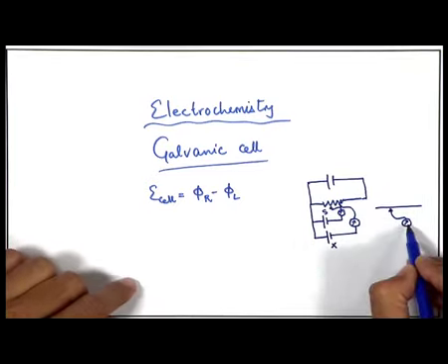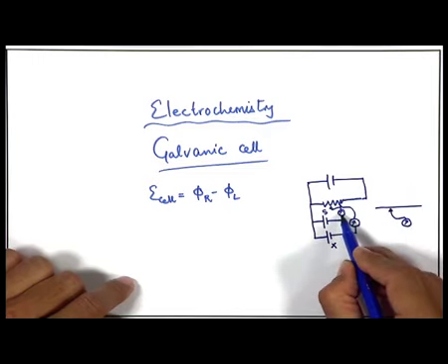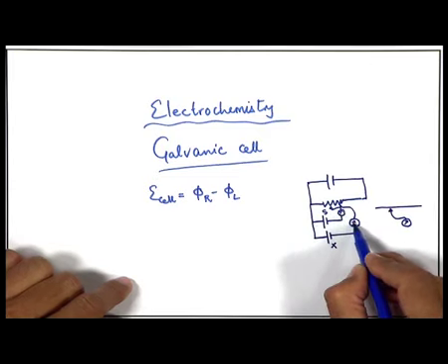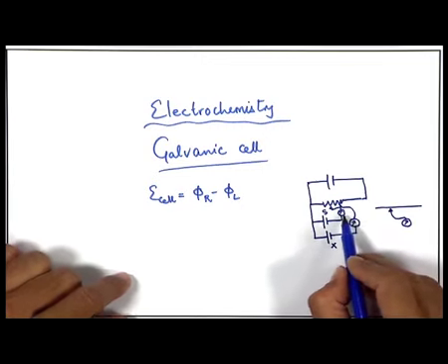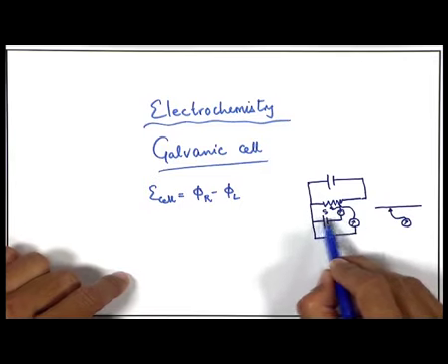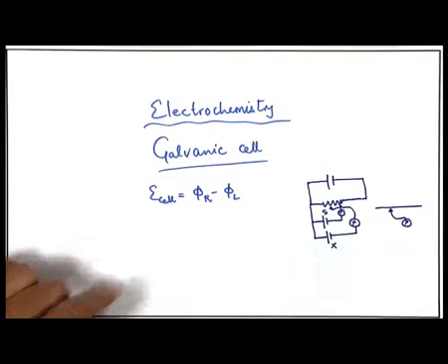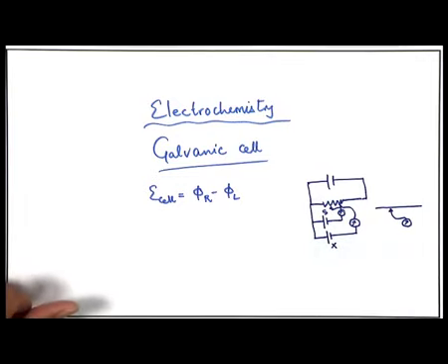So, when this one is having no deflection, then the corresponding lengths will be proportional to the potential difference or EMF of this cell, and then taking the ratio you can find out this cell potential.